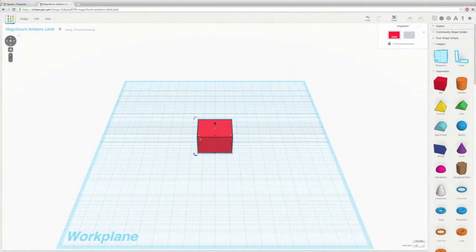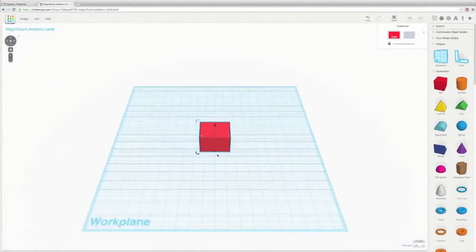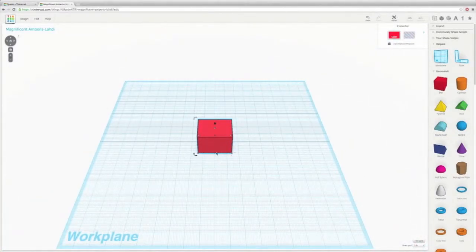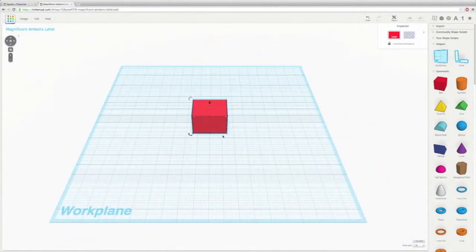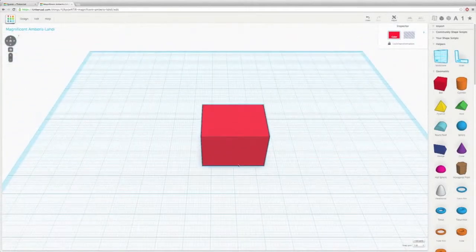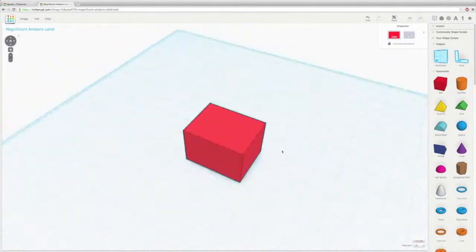Alright, so let's learn some quick ways to move around the object. So if I click off, I can click back on. That's left mouse click. If I scroll the scroll wheel, if you have a 3-button mouse, you can zoom in. Scroll out. Alright, great. If you press down on the scroll wheel, you can pan around the object. Alright, so scroll in, scroll out, pan around, and then last, right-clicking will let you orbit around the object.